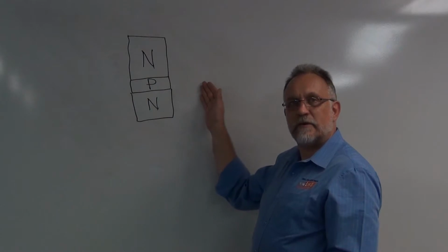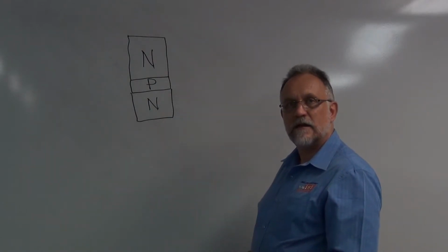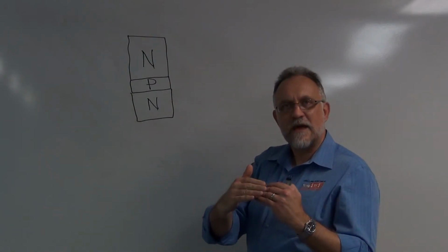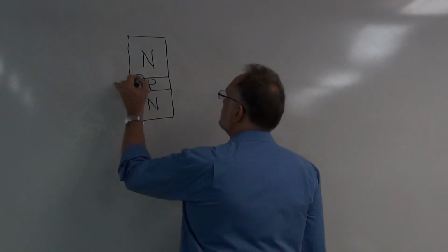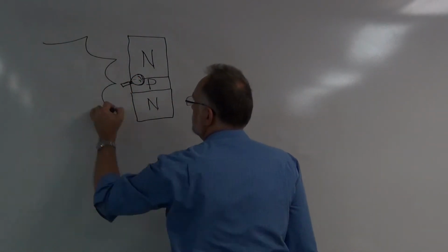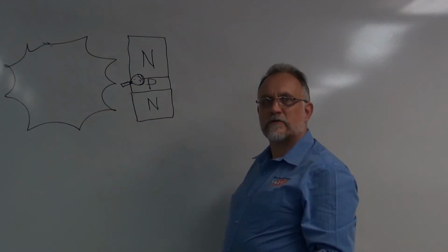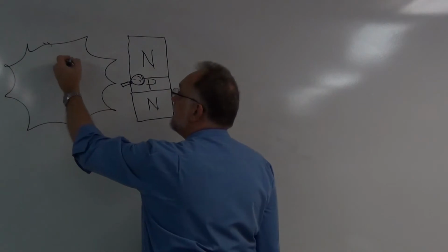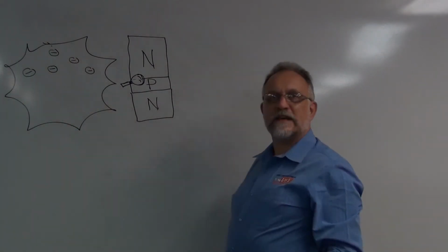When you put N-type and P-type materials together, it creates a junction where the properties of those two layers mix together a little. If we were to look through the microscope at that junction, we would find N-type material here with extra valence electrons. P-type material has a lack of electrons in its structure, and so I'm going to draw the spaces where those electrons belong as electron holes.